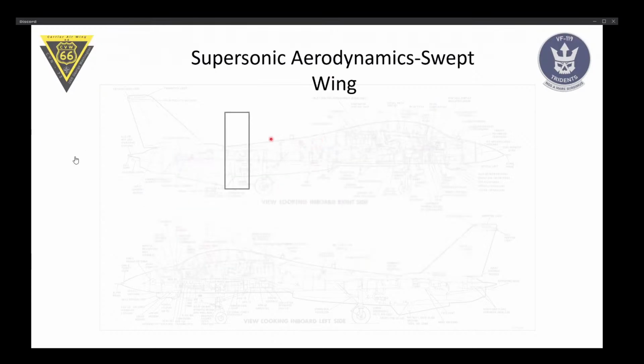What we do is we take our straight wing and we sweep it at a certain angle, let's say 45 degrees. Now what gives us this? Let's say air is flowing around that wing at some speed, and then we can decompose that vector into a component normal to the leading edge and parallel to the leading edge. The component parallel to the leading edge doesn't affect our aerodynamic properties. This is not correct, but as a first assumption, it can be valid for the mathematical formulation.